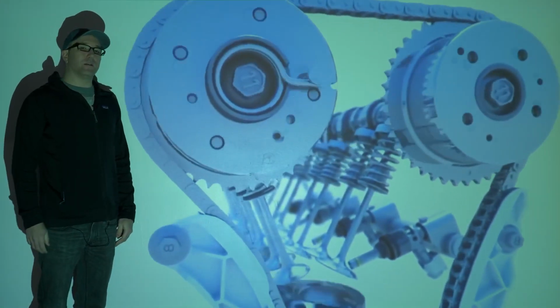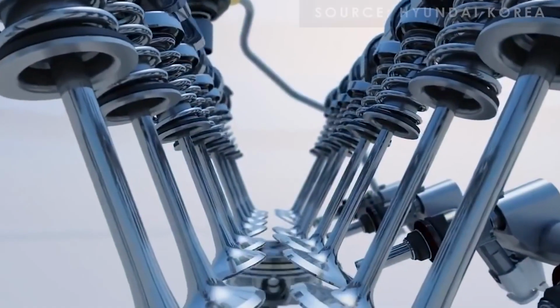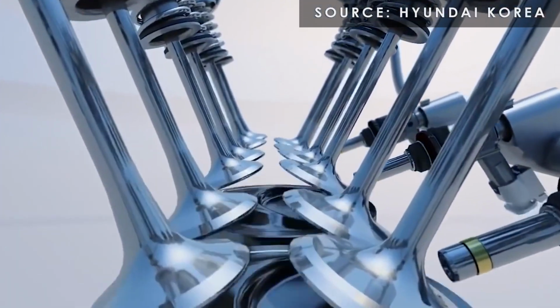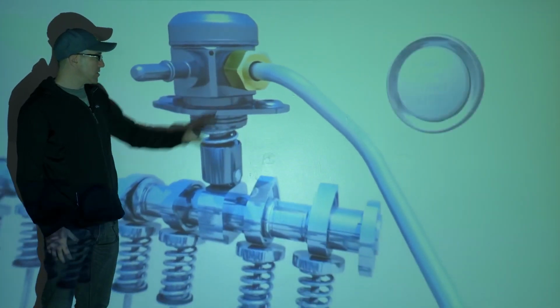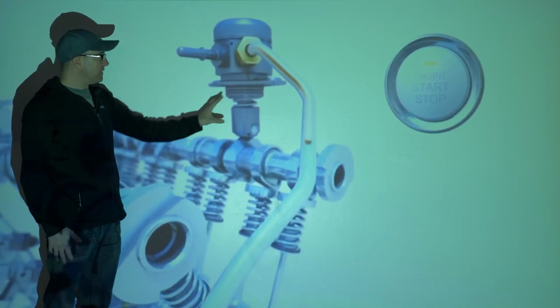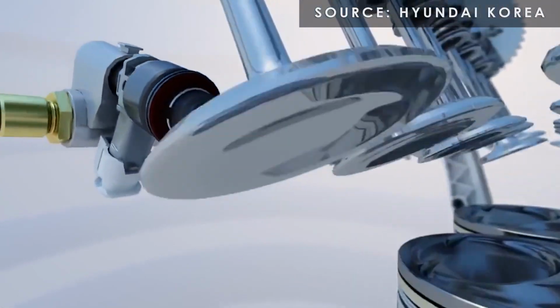Now it's time to talk a little bit more about how this works and the advantages of direct injection. And this is a 3D model by Hyundai for their direct injected motors. Now, let's go back to how this works a little bit. You have low pressure fuel coming from the fuel tank pump into this high pressure module that is cam driven. As the cam lobe spins this, it creates high pressure fuel down the high pressure line all the way to the direct injectors.